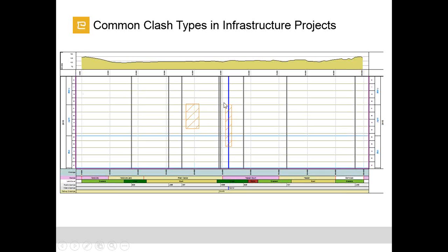We can see this in our drainage, and during this time period. So it's starting from the beginning of April and finishing half of March. So we are not allowed to work in this period on this distance scale. And here what we see is another rectangle, which is representing the environmental restriction. They say that maybe there is a very rare plantation, or maybe there is some bird nesting, and for some reason there is a regulation and we cannot work on these kilometers in April.